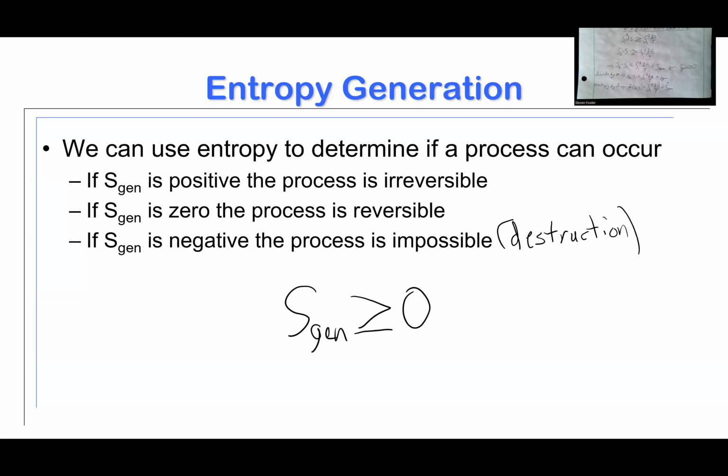If you determine that you have destroyed entropy, and this goes for my students, this goes for anybody out there on the internet, I want you to do two things. First thing I want you to do is double check everything. I want you to check all your units. Check whatever devices you're using to take measurements, make sure they're working correctly, make sure you have the right units, make sure all your measurements are good and your algebra is good.